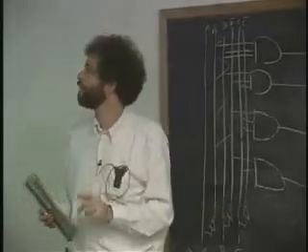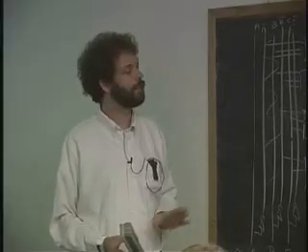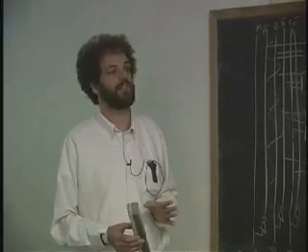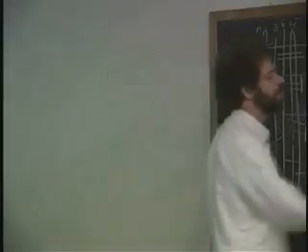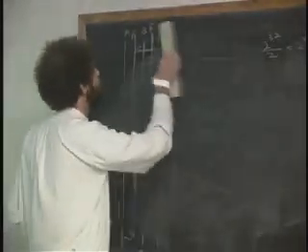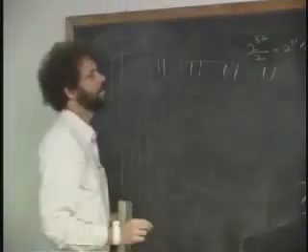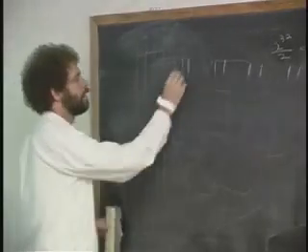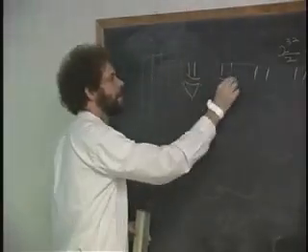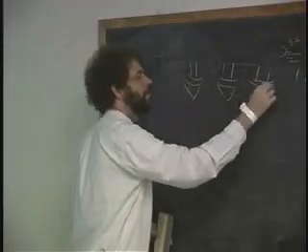And the wonderful thing about the adder is that it gives us an example of one function in particular, the parity function, for which sum of products is absolutely the worst thing that you could do. So what's a better thing that you could do? Use XOR gates. Because XOR gates sort of have an intrinsic ability to do parity to begin with, and if I have a desire to do parity of n bits, what I'm going to do, let's say I want to do a parity function of 8 bits. I take a set of XOR gates like this, each of them with only 2 inputs.